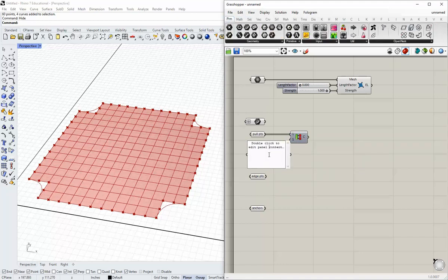All right, so I'm going to go to Panel, because basically I want to take the 3 points in order and put them in their own little list. So let's hover over this. Now we have 4 lists of 3 points each, and because we put those points in order, the same order as the curves, that 0, 0 list there with 3 points will correspond to the 0, 0 list here with 1 curve, and it's the right curve.